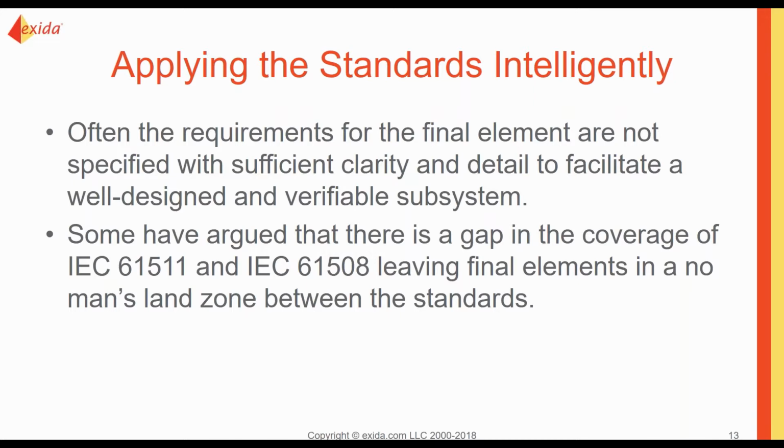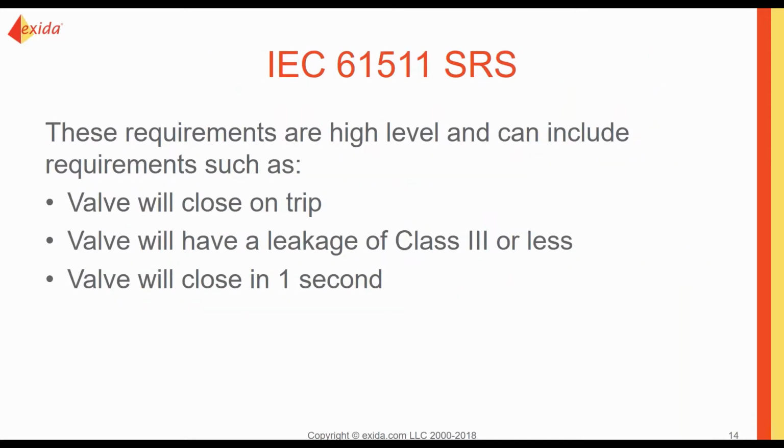So I've heard some people say, you know what, we need a different standard. 61511 doesn't do it, 61508 doesn't do it, so we've got this undefined area, we need a different standard. I don't think that's true. So let's take a look, for example, at the 61511 SRS. We'll often get a top level requirement such as the valve will close, it'll have this leakage class, and here's the time it needs to move. But this really is, we could say, the final element assembly needs to achieve this.